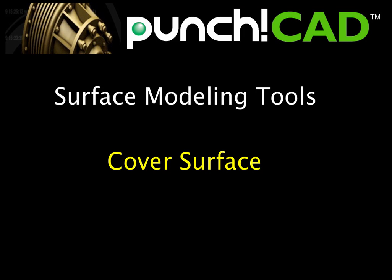In today's video, we're going to look at surface modeling tools, specifically cover surfaces. A cover surface creates a surface from a closed loop of curves. It also includes options for tangencies, guide curves, and bulge factors. In this video, we're going to demonstrate making covers from simple planar curves, n-sided three-dimensional curves, covers with guides, and tangent covers.